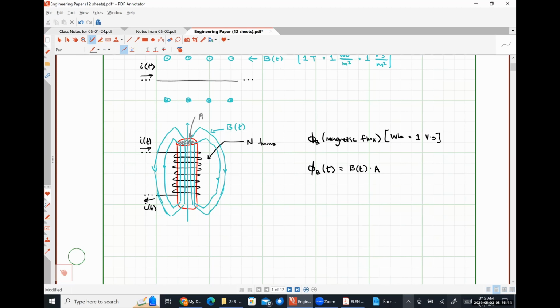So inside the coil, we have a very large magnetic flux density because we have all of those field lines passing through a very small amount of space. And outside of the coil, we have a very, very low magnetic flux density because we're allowing those field lines to pass through effectively all of the air outside of the coil, okay? So wrapping our wire around a core like this gives us a region where we have a very, very strong magnetic flux density vector, right? That's the reason we use solenoidal coils, toroidal coils, all of that kind of good stuff.